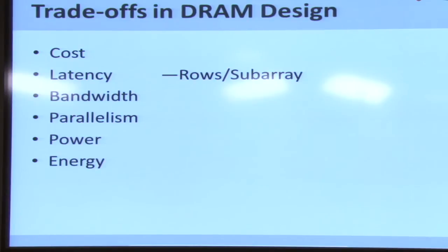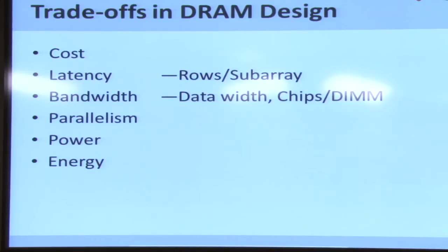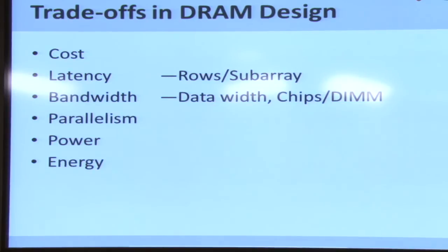Cost. Because now if I have to get 512 bits from the row buffer to the bank I/O logic, means I have to build 512 wires that span the entire chip. Cost. Okay. So in some sense, the trade-offs are basically the data width of each chip, which we can increase at a cost, or the number of chips per DIMM. We can also increase the number of chips per DIMM. But again, like we have discussed, having more chips in each DIMM means you are spending more power for each access. Right now, I'm activating more chips for each access.